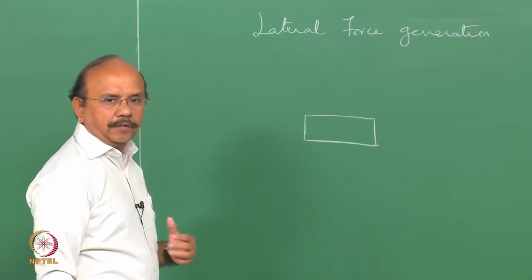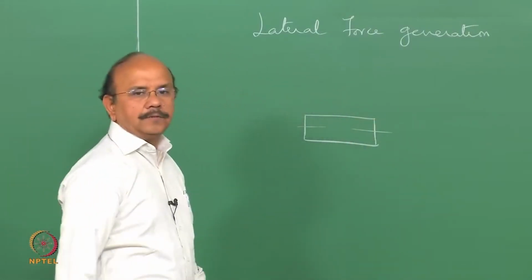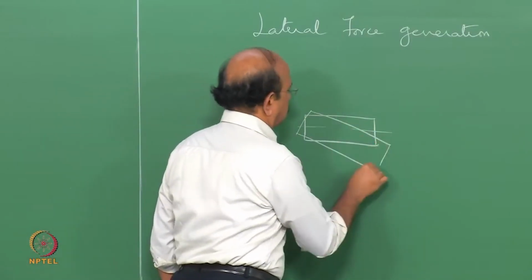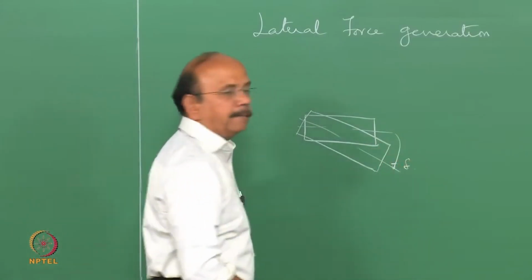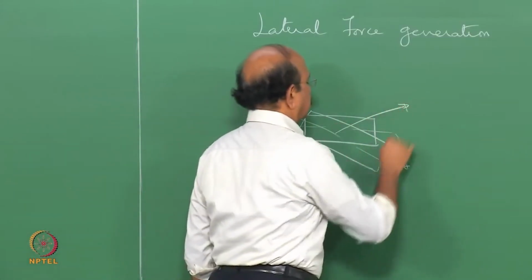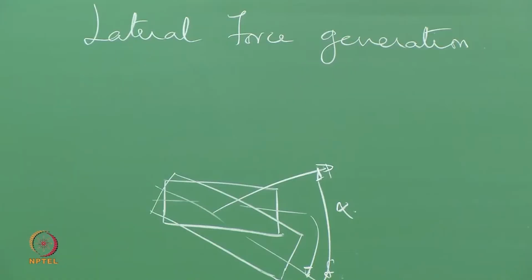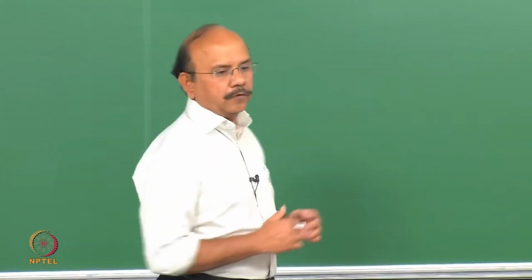So if this is the straight running tire, and that is the central part, and then you give a steering input, which we said is delta, then there is a slip angle produced, and so on. And we saw that the distortion causes the centripetal force that's required in order to sustain the centripetal acceleration. In other words, it cancels out the D'Alembert's force called the centrifugal force.